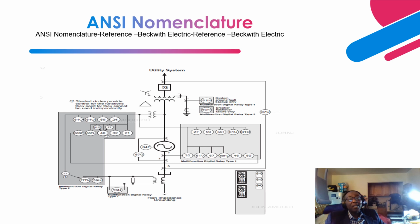When it senses that current flow after a period of time, then it knows for sure that this breaker has not tripped. Then it's going to time out and activate other breakers that are in close proximity, especially breakers on the AC grid, to trip, to prevent the flow of current and cascading into the AC grid.